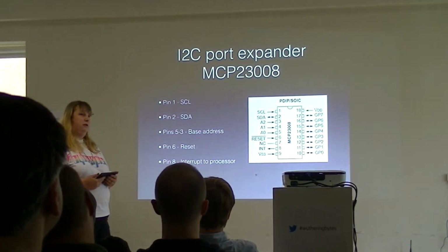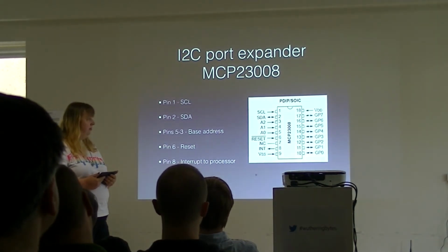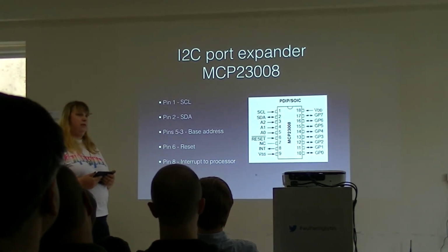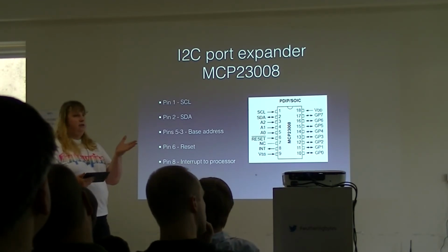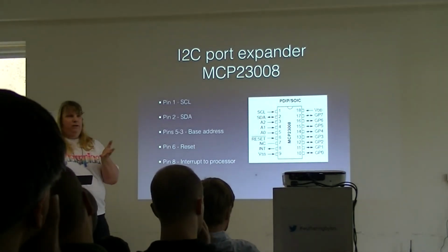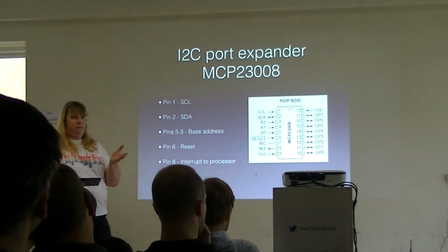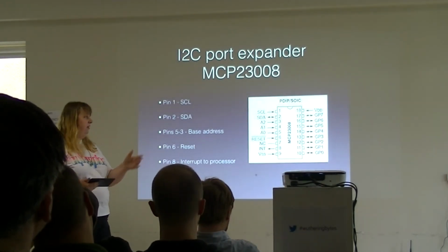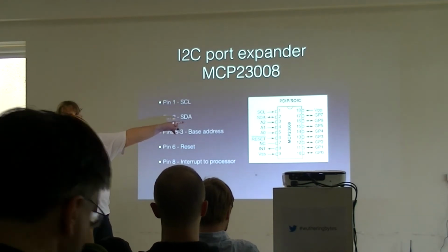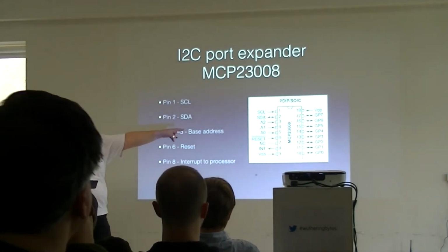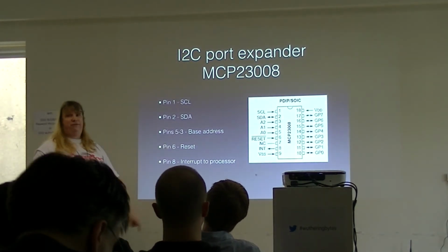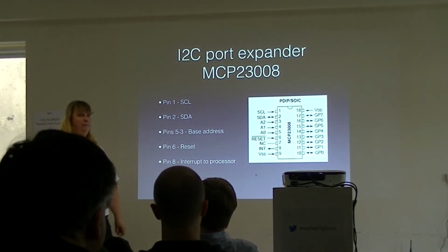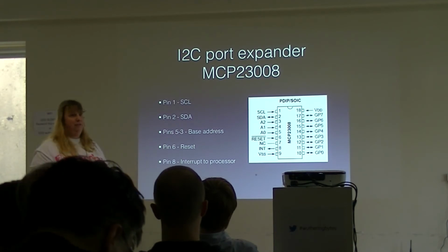Useful I2C chip: it gives you 8 GPIO lines off of an I2C bus. As I said earlier, you can blow up GPIO pins on your Pi, short them, or use the wrong voltage or stuff like that. I just use one of them hanging off the I2C bus on the Pi, and then I put everything on those. They're about £1.50. If I blow it up, it goes in the bin, I get another one.